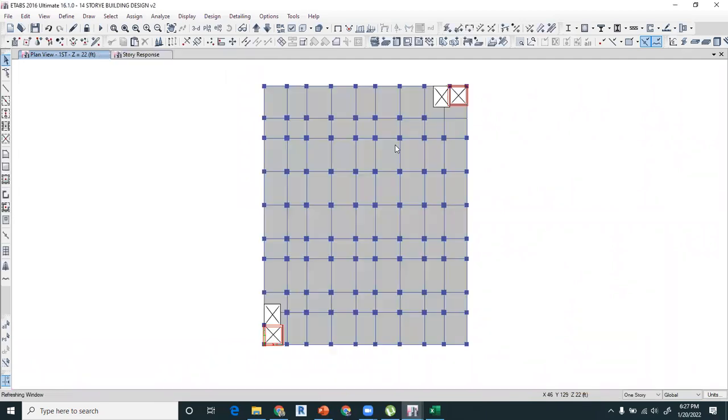You can see that if I provide the shear walls in the X direction, it will give enough stiffness to the structure not to deflect or drift in that direction. So whenever you have drift in an X or Y direction, you have to provide the shear wall parallel to that direction. So this is our X direction.